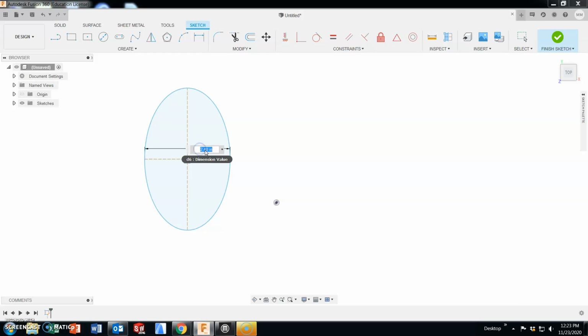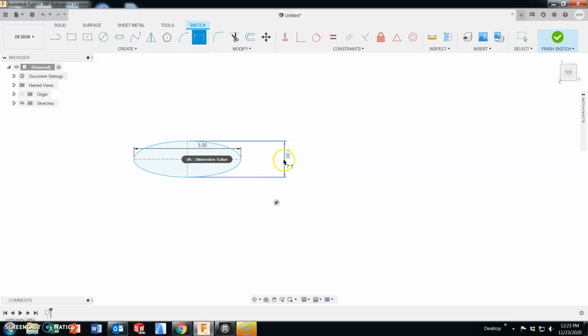There is a guideline here. I could set this to be 3 and then change this to be 1 to manipulate the axis. But you are controlling 2 radii. So ellipse again, center, 1 radius, 2nd distance, and then you can change these however you see fit.